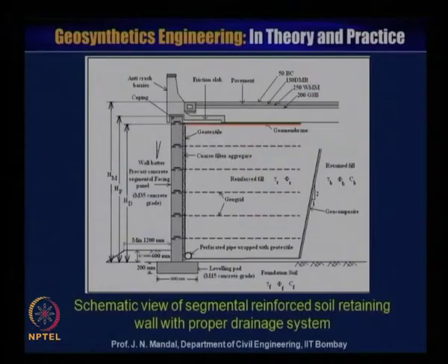Now, here is a schematic view of a segmental reinforced soil retaining wall with proper drainage system. This is the wall, this is the number of layers of the reinforcement, that is geogrid material, and at the back we are providing a proper geocomposite drainage.